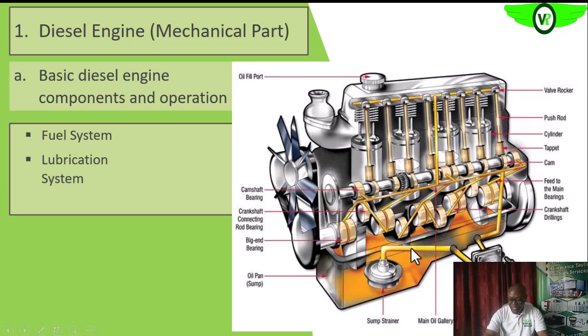Okay, we have a pump that pressurizes the oil through the filter before it is sent into the engine. You remember those hoses that we talked about in the crankshaft? Okay, so it is sent through those hoses to the various joiners within the crankshaft, and then you see it coming on top of the valve cover, and as it is flowing down, it lubricates all other moving parts. Okay, that will flow down through to the camshaft and then back into the oil sump.